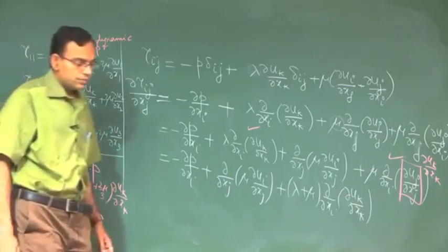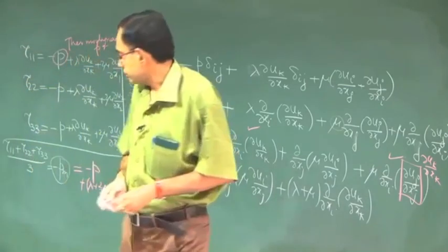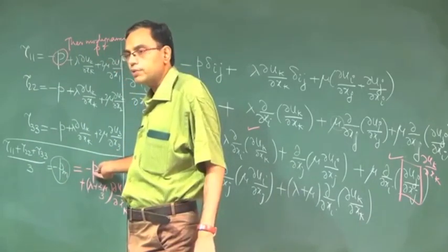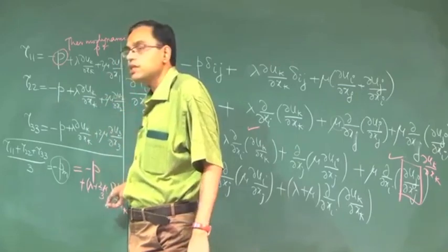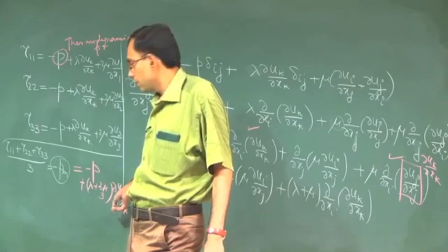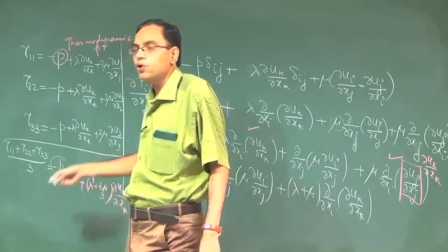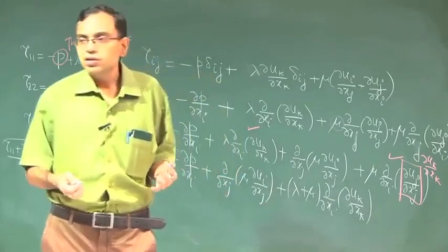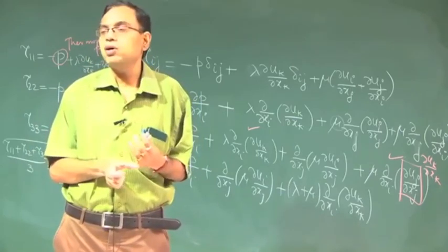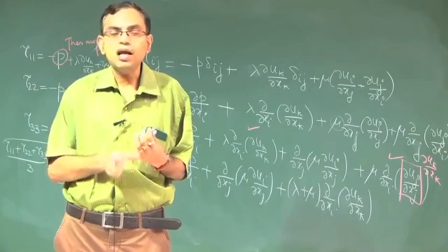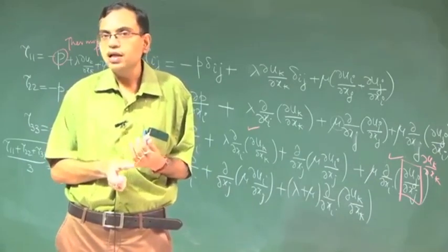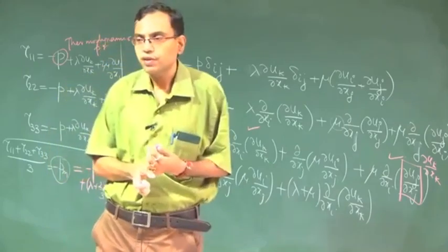Now, the very important question: will the mechanical pressure be equal to thermodynamic pressure? In one case obviously yes, when it is incompressible flow. But when it is compressible flow, there is nothing fundamental which tells us that the mechanical pressure must be equal to thermodynamic pressure until and unless we hypothesize it, and the hypothesization can be through some argument.